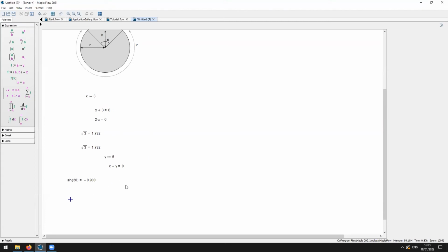Now, a very common function is fsolve. Fsolve is a numeric equation solver. So, for example, if z plus log z is equal to 3, then z is about 2.2. That's a very simple example of fsolve. It's capable of much more. There's a level of detail that we can go into about the syntax of fsolve, the various options, but we're not going to touch that in this webinar.